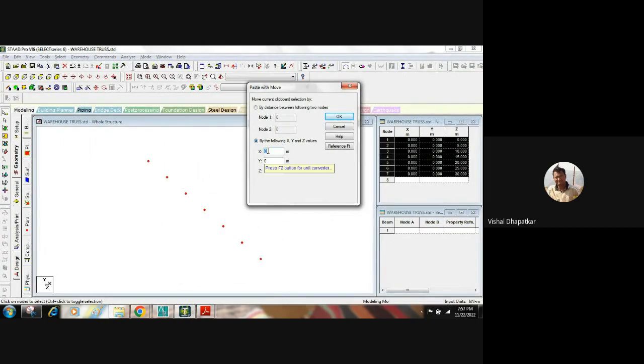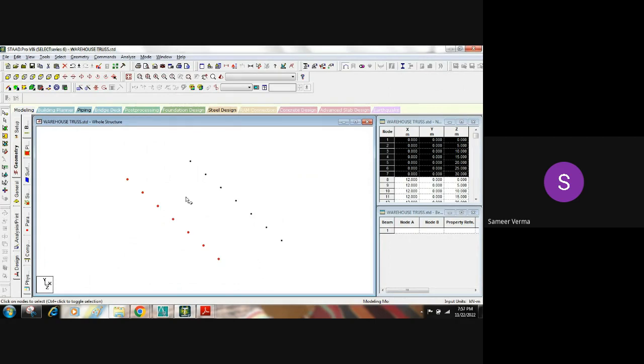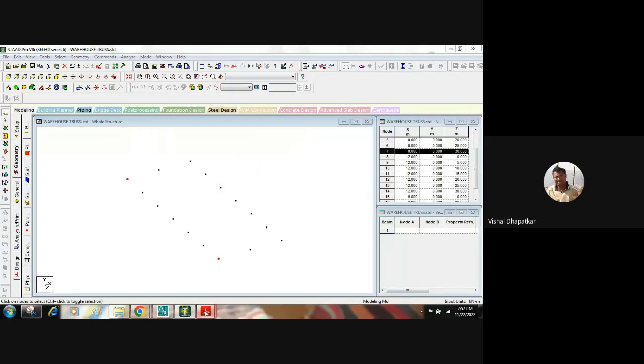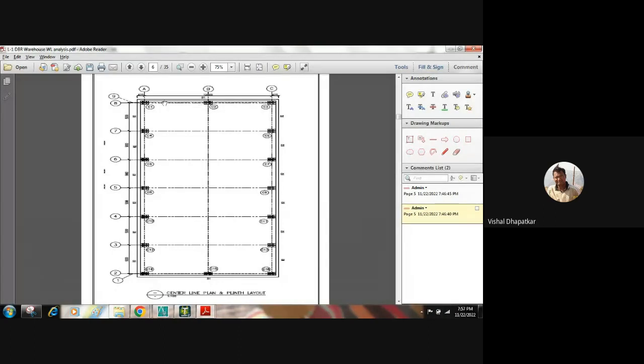Anyone? So the cladding or covering material, so that it can break it in between, otherwise it would become large. Correct. So we need this column. This is gable and column, and when we are running the cladding runner, we cannot span it for 12 meters, right? So in order to cut that cladding runner, or shorten the span of the cladding runner, we have to consider one column here, so that we can place the cladding runner here, and then we can support the sheeting over here. Otherwise 12 meter length will be huge and it will buckle in minor direction.